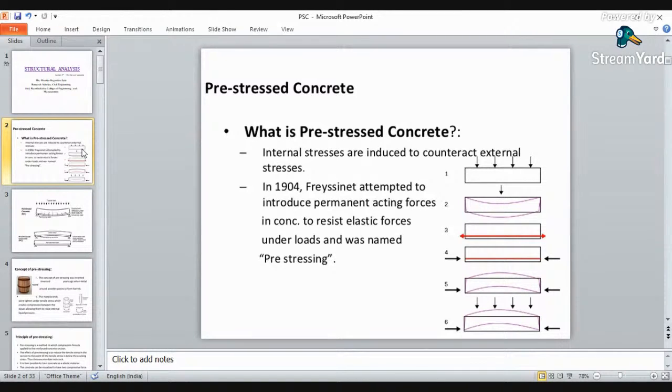In case of reinforced concrete, we have seen the day before yesterday that deflection has another impact. Reinforced concrete is made up of steel, which is much more elastic than concrete itself. In order to mobilize the strength of your steel, first it has to stretch a little bit, but unlike steel, concrete is very much brittle, so it will not stretch. So when we test RCC, if it is under-reinforced, then your failure will be a ductile failure, and if it is an over-reinforced section, then your failure will be a sudden failure, or brittle failure.